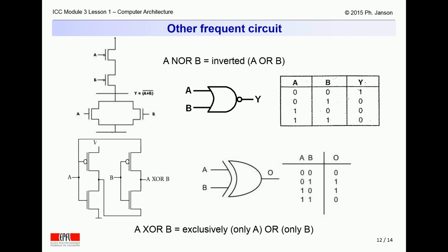On the contrary, when A and B differ, one of the NMOS transistors and the diagonally opposed PMOS transistor will be closed, while the other two transistors will be opened. Thus, the output will be connected to A when A is 1, and it will be connected to NOT A when A is 0, meaning that this output is going to be 1 in either case.